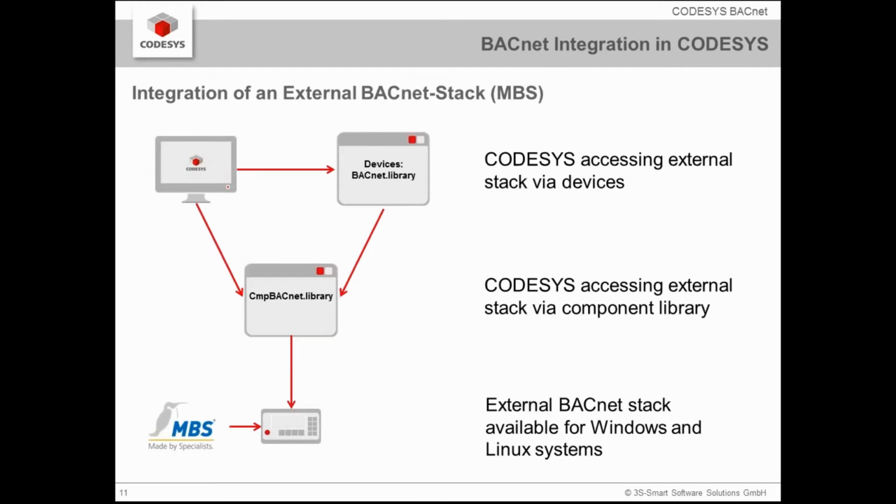For the product CODESYS BACnet, we integrated an external BACnet stack from the company MBS. And we implemented two ways of accessing this external stack. The one way is via CODESYS devices. The other way is via a component library in the runtime system. The external BACnet stack we provide is available for Windows and Linux systems.